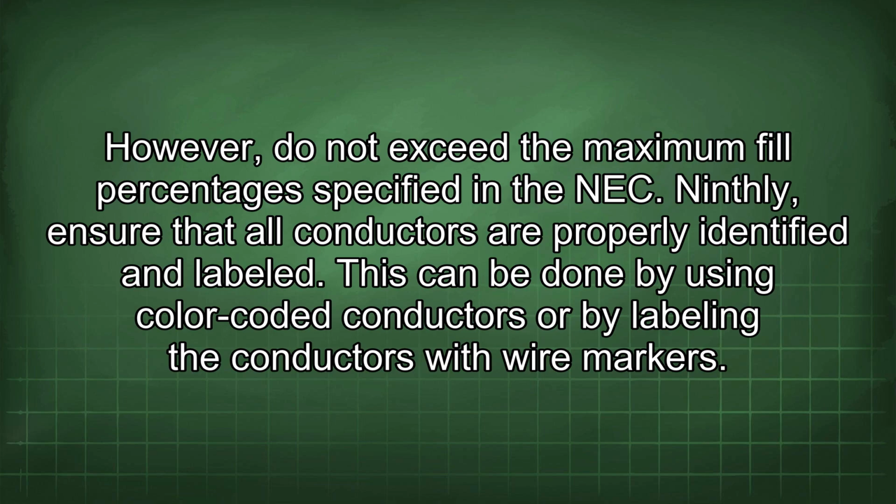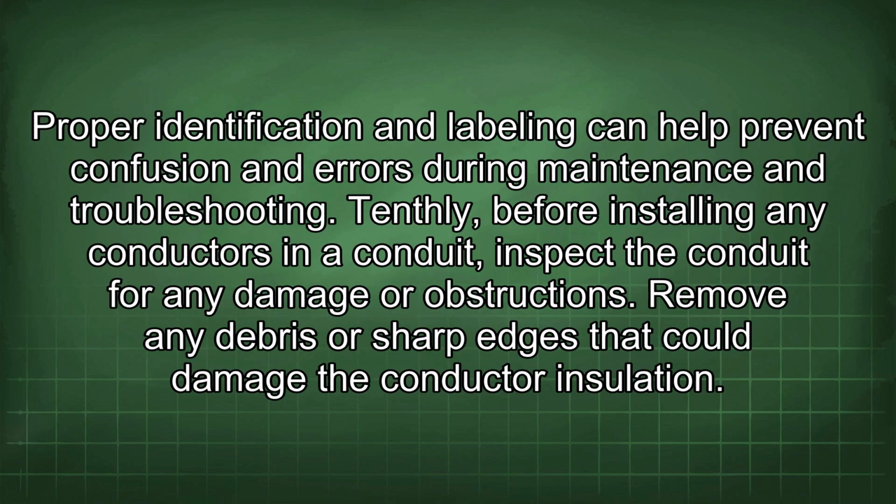Ninthly, ensure that all conductors are properly identified and labeled. This can be done by using color-coded conductors or by labeling the conductors with wire markers. Proper identification and labeling can help prevent confusion and errors during maintenance and troubleshooting.